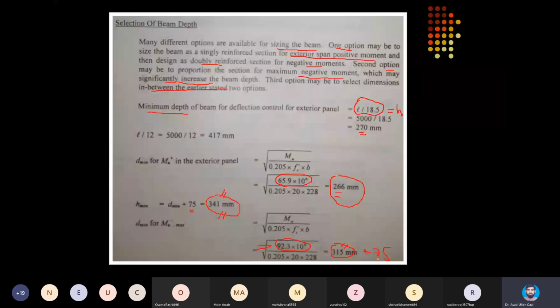It is important to note that 1, 3, and 5, when slab is present on top, are rectangular sections, although apparently they are T-shaped, but since tension is present on top, still you will be dealing with them like rectangular beam design sections.